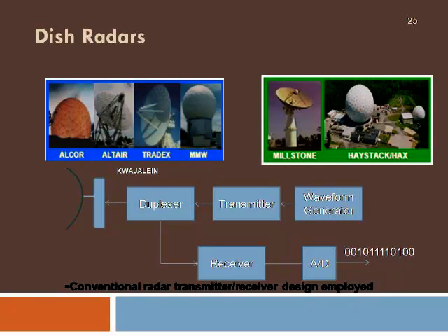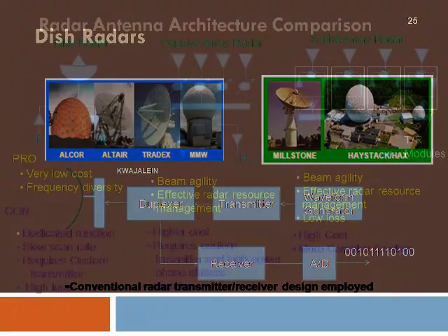The output is directly connected to the antenna from the received signal of the antenna via a duplexer. We give that input to the receiver, which is converting it into a low frequency one, and this analog output is converted to digital form for further processing by this. This is the most conventional block diagram of a radar system, which is used in most of the radars that are shown in the slide there.